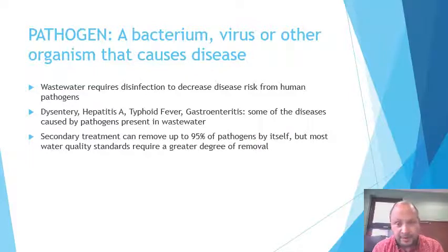So secondary treatment actually would remove, in a lot of cases, the majority of pathogenic material, but we're still going to have some leftover that we need to remove. So that's why disinfection. Actually, here at our plant, and probably most plants around Ohio, we are not required to disinfect for a couple months of the year in the middle of the winter.